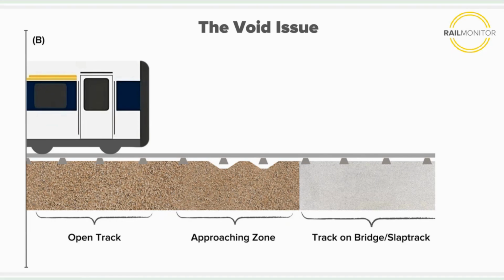The cause of this is that the track will start pumping or moving more and more, and this will of course also affect the degradation of the ballast, and over time the rail. The location is typically, as said before, critical in the transition zone between these different structures of ballast and concrete. It could be in embankments, but also in tunnel portals.